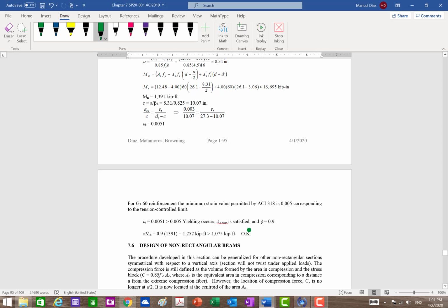So when you're doing compression steel and ductility does not satisfy, there is no need to panic. You just have to use your concept. If I add more compression steel, I will improve my ductility. If I reduce the tension steel because I may have exaggerated, then I can also improve my ductility. So keep those things in mind.